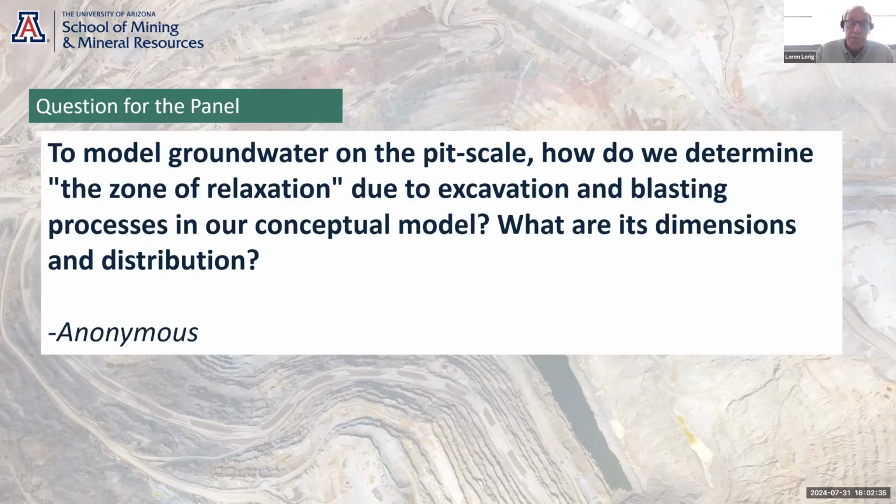So if we have a pit that's a kilometer deep, the zone of relaxation is much more than a pit that's 100 meters deep. And so we've kind of come to a general understanding that it's about a quarter to a third of the depth of mining, but it's very crude.